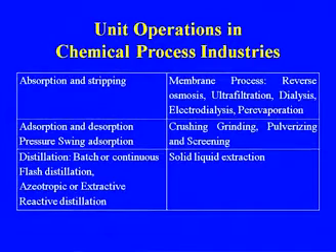crushing, grinding, pulverizing and screening, because these are some of the very initial stages. You take the case of the cement industry, a lot of changes have taken place in the unit operation for crushing or pulverizing. Earlier in the boiler, we were using non-pulverized coal. Now, because high capacity boilers are there, we are using pulverized coal. In cement manufacture, we have crushing and grinding. Earlier we used to have ball mill grinding, now we have the vertical roll mill or the press roll. Then the solid liquid extraction.